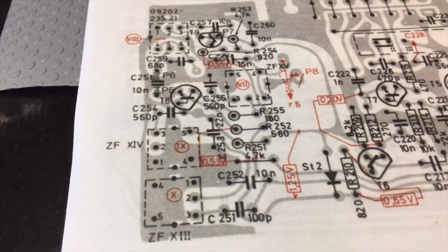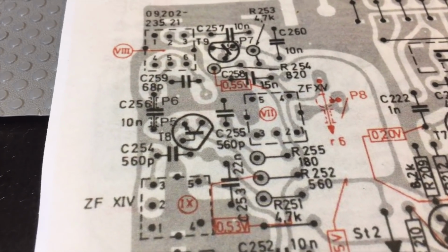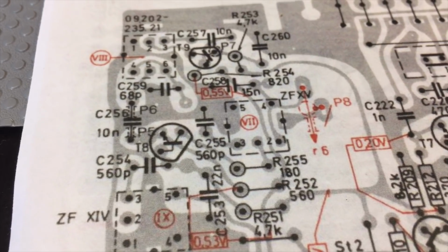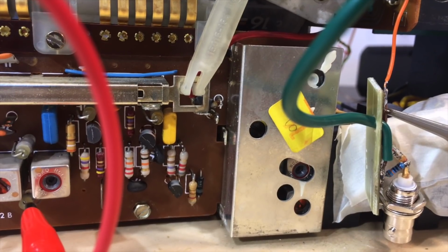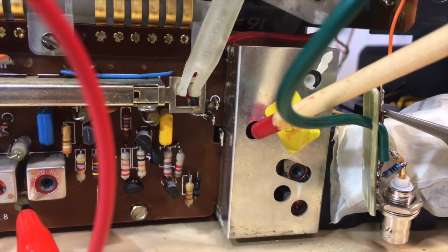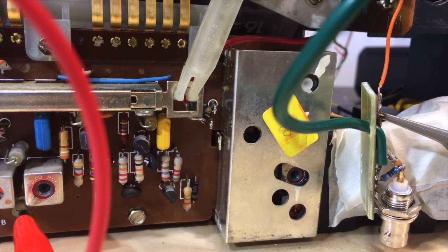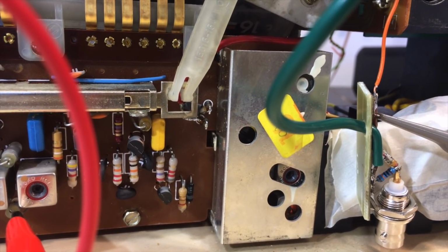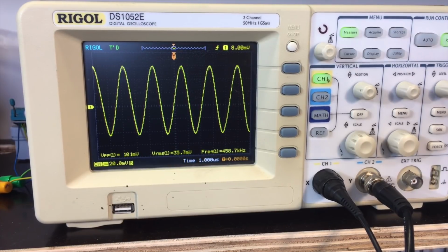C7 is here. And that is inside there. So that's what I'm going to adjust now. There's my peak. 7 is done, and that's all on the 2 megahertz line. Right, one more step completed.